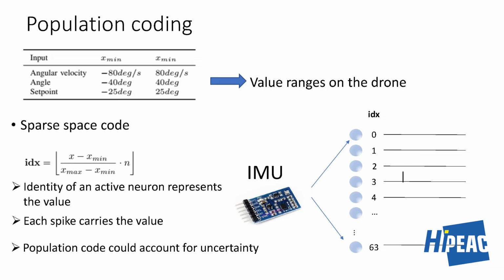It doesn't have to be so strict, because when I measure my angle with this inertia measurement unit, I could project a little Gaussian smoothing function, so that it's not one-to-one, one measurement, but I have some kind of uncertainty. Let's say I have 100 neurons here, and the input mapping is little Gaussians with a little blur.